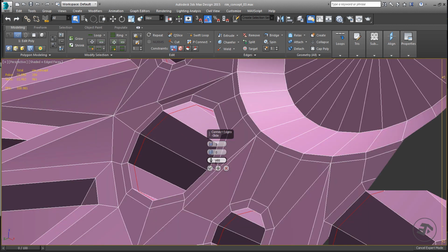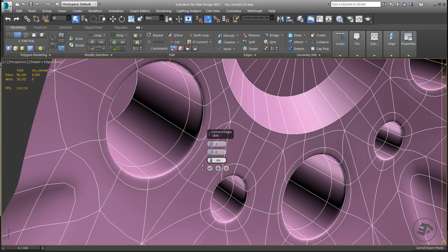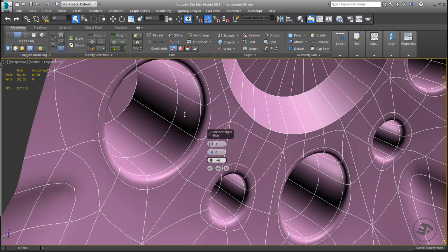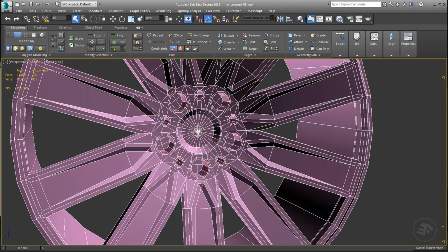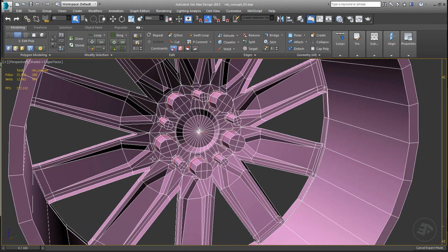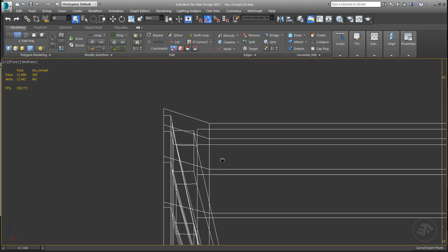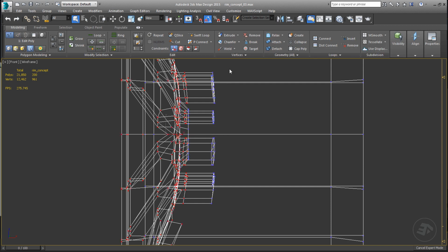The supportive loops can also be added to create and control the chamfering effect, as shown. The soft selection did affect some background surfaces, which are required to be planar. Select all the background vertices of the bended area. Align them on the Z-axis.